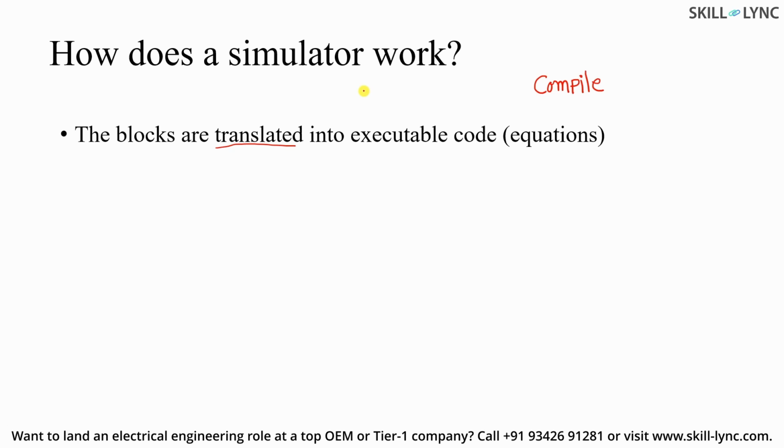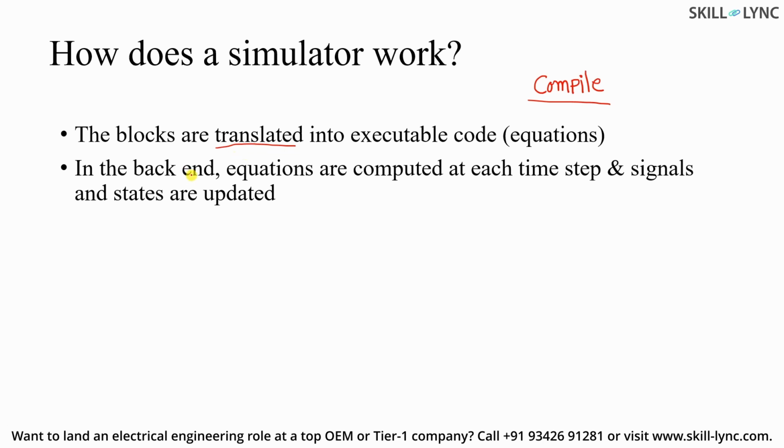So a simulator, before running, is going to compile your block or compile your model where all the blocks are present. Now after this, once it is translated in the backend, equations are computed. So basically MATLAB and Simulink is a technical computing tool where all the equations are computed at each time step and signals and states are updated.